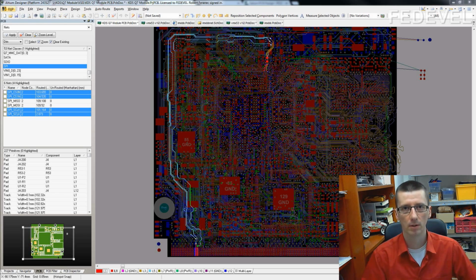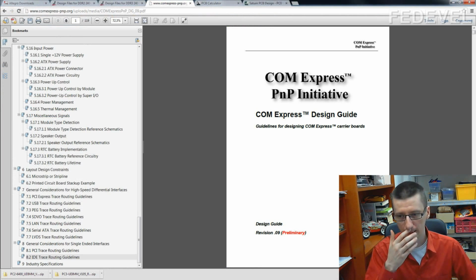That's our goal. How do we know what kind of impedance we have to match? We use the design guide. Read the design guide of your chip manufacturer. They will specify it. As an example, I will use this design guide, which gives us examples of basic interfaces.